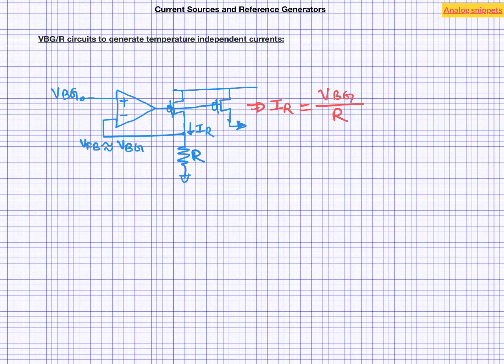Obviously, this circuit has additional design, area and power cost associated with it. But that is the price we have to pay for a more accurate current reference. Now, because of the process variation of this poly resistor, the current generated may not be good enough for some precision applications. By far the most commonly used method to improve the precision is trimming. Now, since in conventional bandgap the reference voltage is almost fixed, the only option is to trim the resistors. But if we are using this circuit with Banba bandgap architecture, then we can trim the bandgap voltage itself.